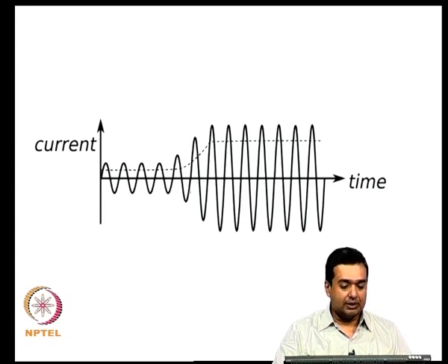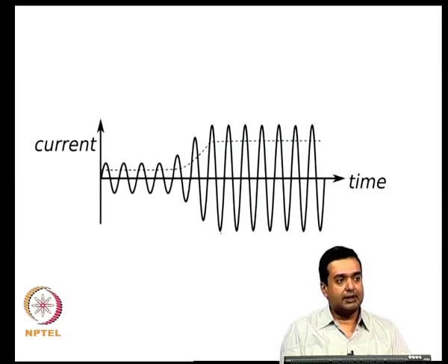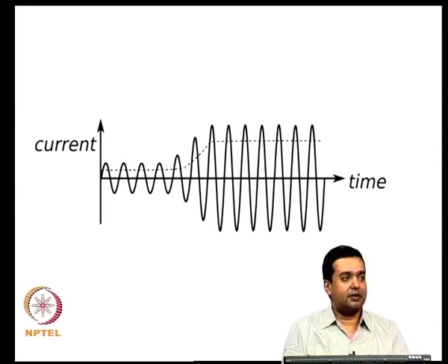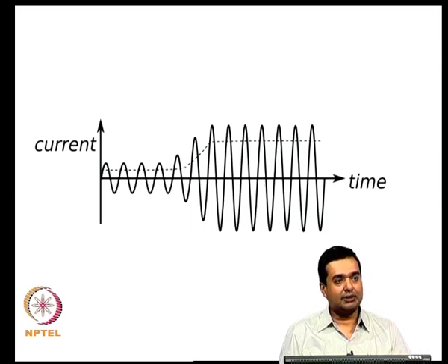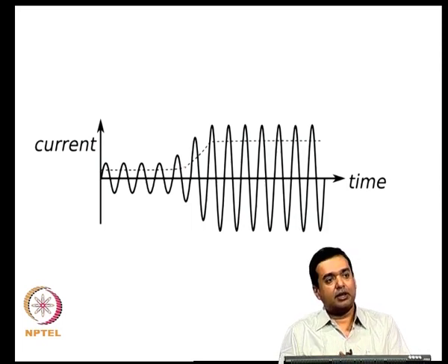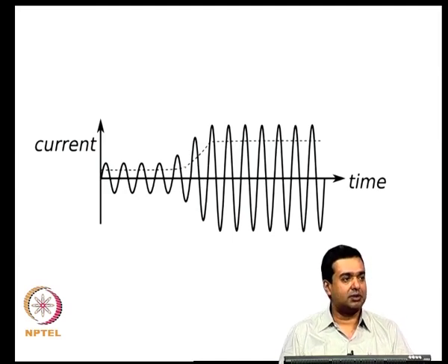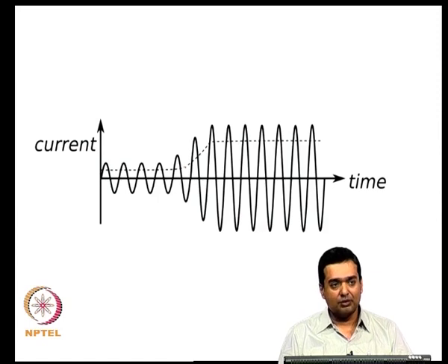On an instantaneous basis from the power electronics perspective, your actual waveform might be a sinusoid, whereas if you are looking at it on an RMS basis, you can think of it as a slowly varying quantity, which can vary on a cycle to cycle basis, and depending on the RMS values, you would decide whether to open a breaker or keep the breaker closed. So, you have to keep the time frame in mind when you are discussing the protection level in these systems.